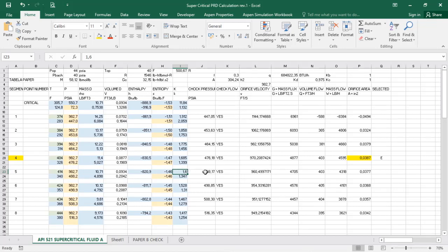Based on that, I am able to do the calculation of the choked pressure using the relief pressure and the CP/CV. Considering that at choked pressure I have constant entropy, I will get this information of choked pressure, add it to my table, and set Aspen Hysys, for instance, or other process simulation software, to reach the pair of pressure and entropy to find the new temperature.